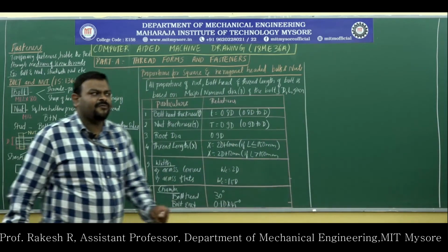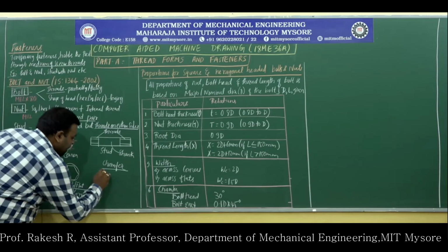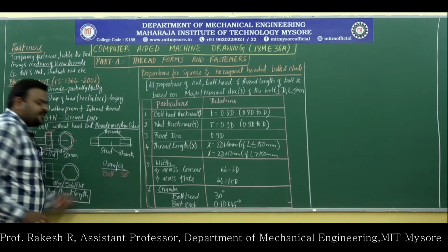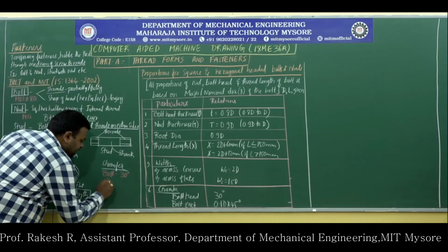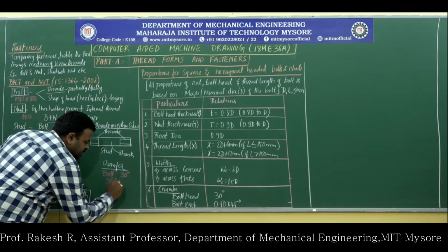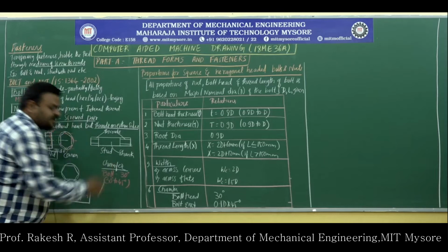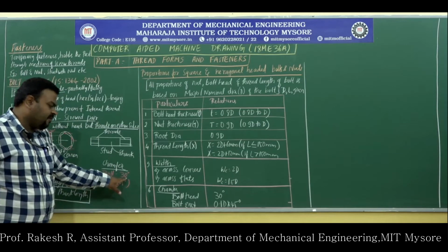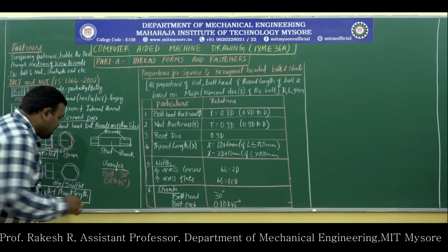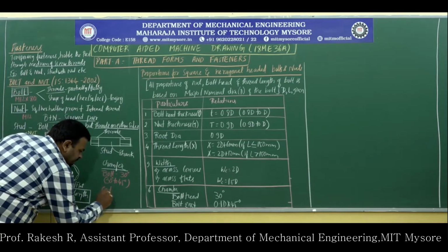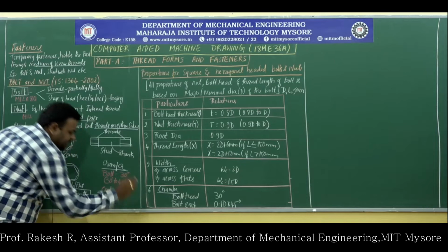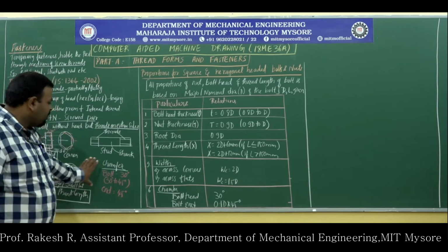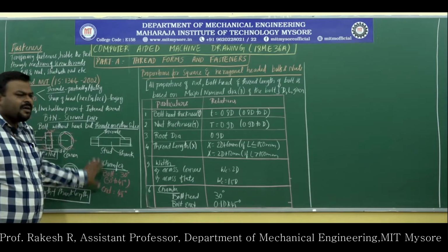Usually for the bolt chamfer, we give 30 degrees. It will range from 30 degrees to 45 degrees based on the length. If the length is more, we sometimes need to give 45 degrees. So the standard we follow is 30 degrees for the bolt, and at the bolt end, we give 45 degrees. These are the standard conventions we use for bolts and nuts.